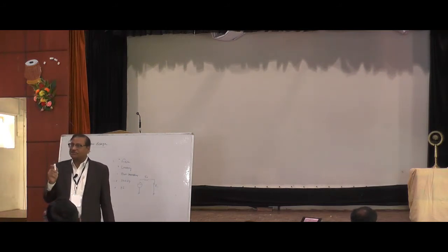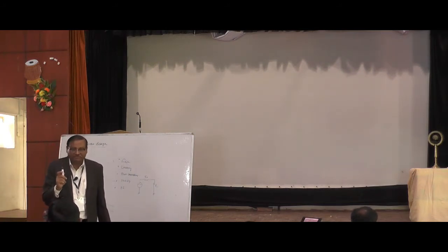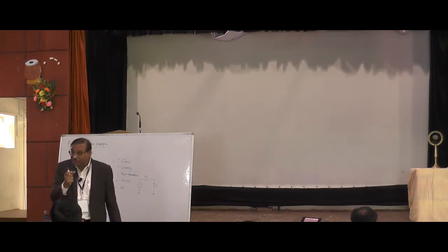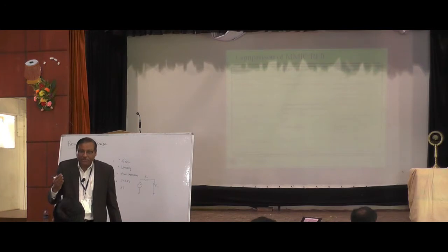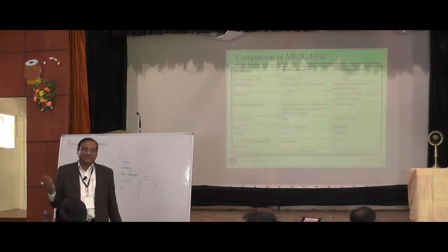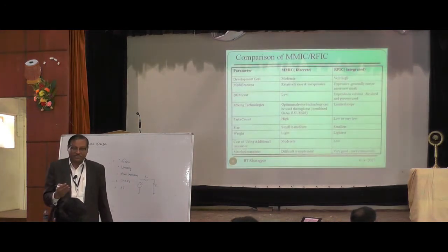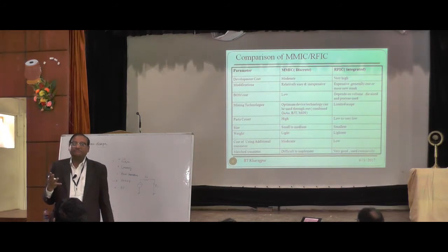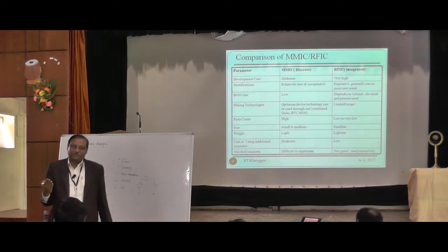That is also the condition for highest gain of an amplifier, because my input signal is being amplified. If the input signal itself gets reduced, I will not get the high gain. Therefore, I need my source impedance to be matched with my load, so the maximum power gets transferred to my load.